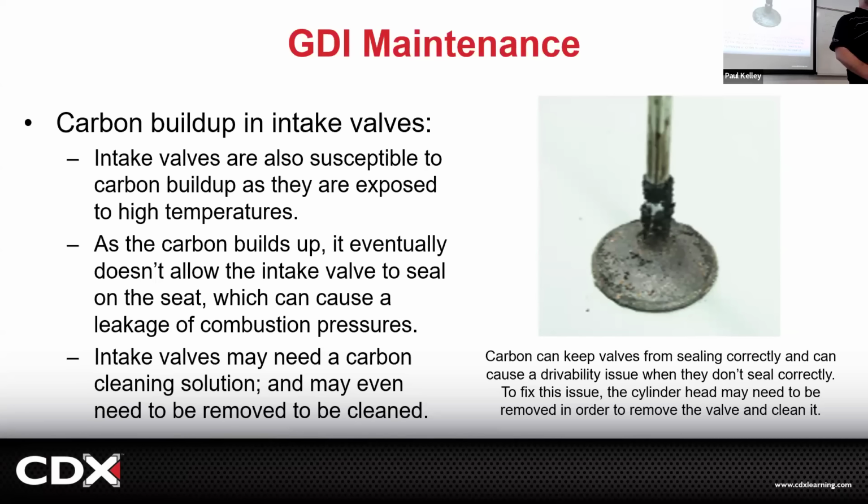No, you can do it with the head on, but you've got to have the intake off and do your walnut blasting. You've got to be able to access that valve pretty well. You know what you could do? You could do a Sea Foam, and it may or may not help a lot, but it'll help a little, where you can put a little hose on your intake and dip your little hose in your little Sea Foam and let the engine slowly but surely pull up a little Sea Foam, and that'll hopefully break some of this up. There's all sorts of ideas.